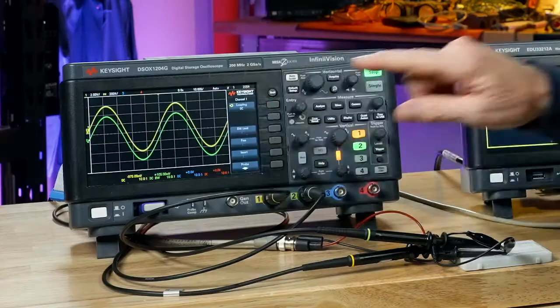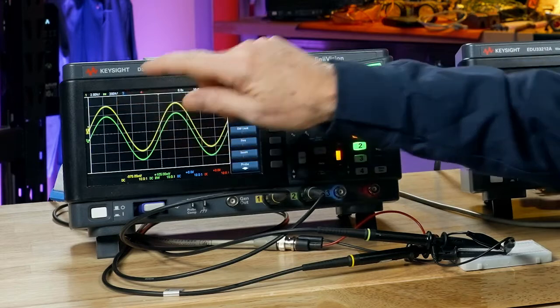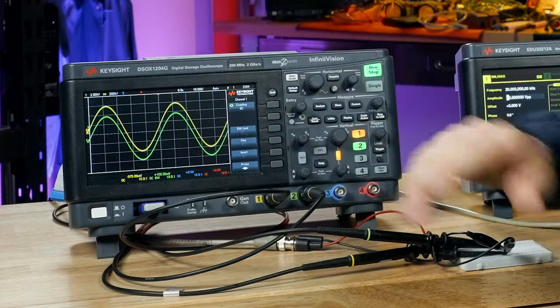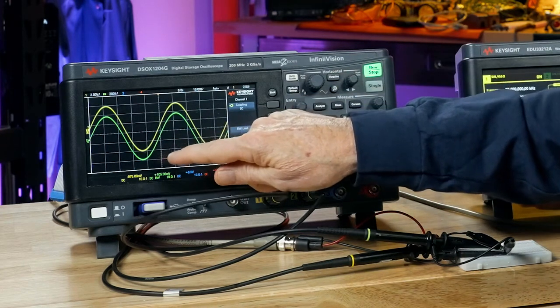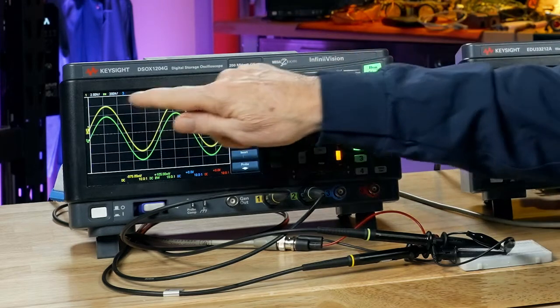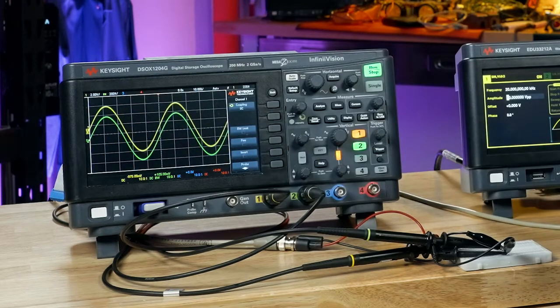Now, what about the channel 2 waveform? It looks like it's the same size as the channel 1 waveform, but it's not really, because the scaling factor says 200 millivolts per division, or 0.2 volts per division. And so we can, again, count the number of divisions, 1, 2, 3, 4, 5, times 200 millivolts per division is about 1 volt. Again, exactly what we expect based on the schematic, the circuit that we're probing.